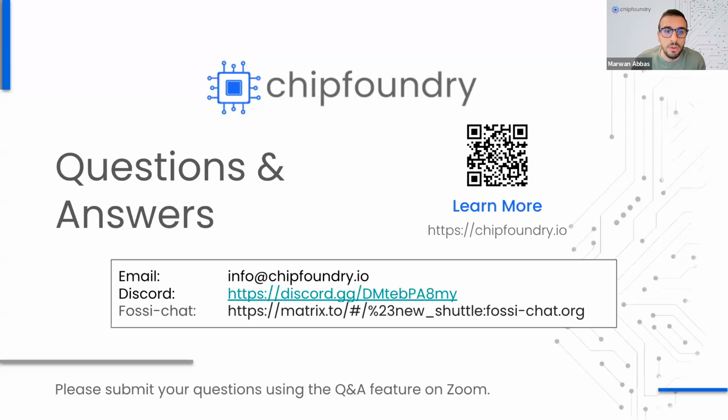Do you also consider timing performance of these designs in pre-checks? We do have an STA flow. It's called timing scripts. You can run them on your design, but they are not part of pre-check. Pre-check only does the physical verification of your design. It doesn't do any functional or timing verification.